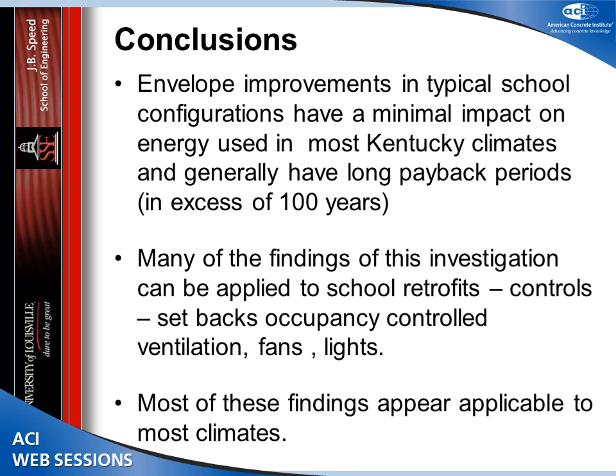Envelope improvements had, for our configuration of school, little effect on the overall energy used, at least for the climates that we investigated and with the limitations of the accuracy of our model. Generally, they had very long payback periods, in excess of 100 years.